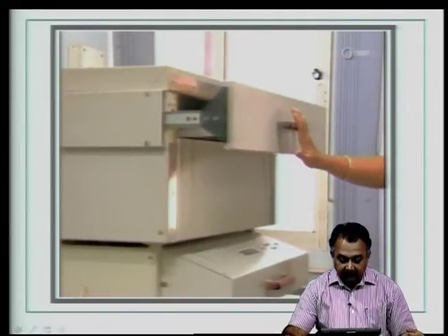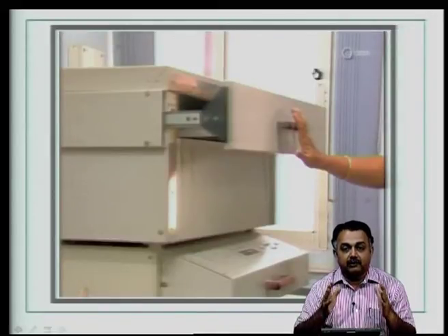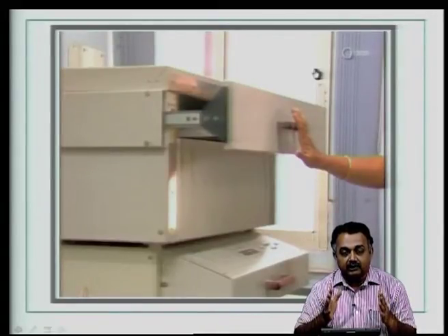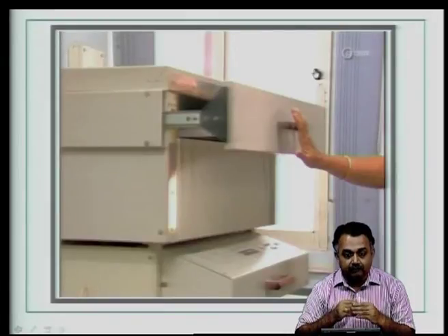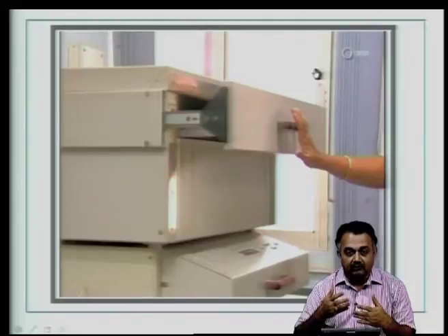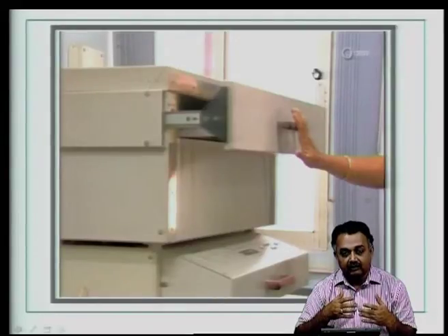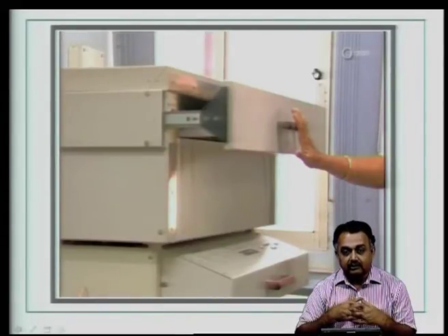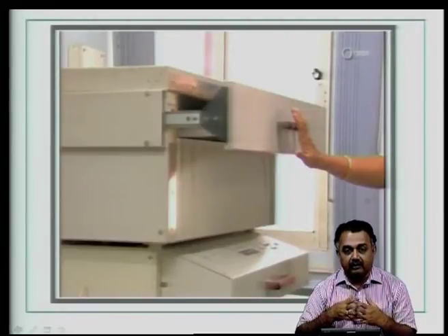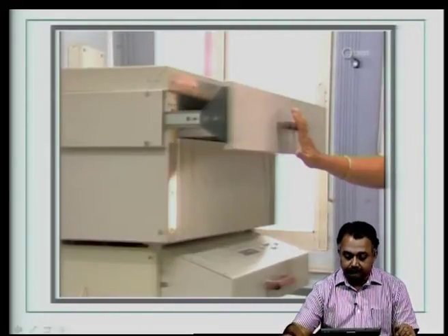Here, before we actually start, you have to create a temperature profile, which means you have to understand at what temperature the solder paste is going to melt, what is your glass transition temperature of the board. I think you are aware of the glass transition temperature which we have discussed, and then are there any components that can fail at that peak temperature. So, these three important criteria have to be carefully noted before you move into the reflow soldering process.